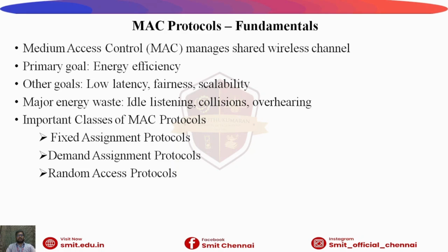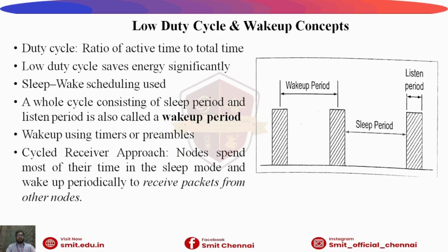So the next topic is low duty cycle and wake-up concepts. A key concept in wireless sensor network MAC design is the duty cycle. The duty cycle is defined as the ratio of active time to total time. Low duty cycle means nodes remain asleep most of the time. This significantly reduces energy consumption. Nodes follow a sleep-wake schedule where the sleep period means the radio is turned off, and the listen period means the radio is turned on. A complete sleep plus listen period is called a wake-up cycle.